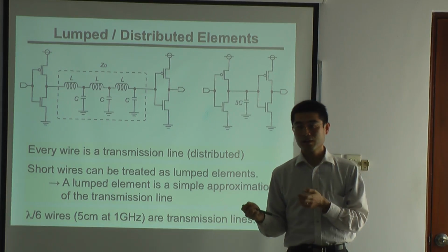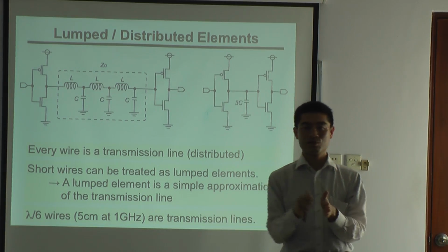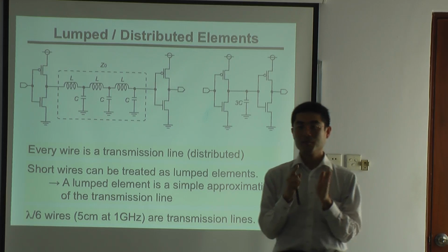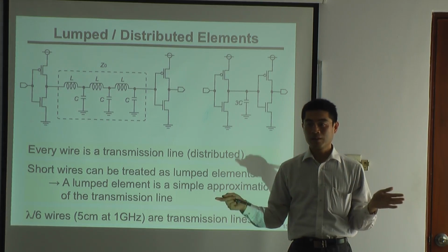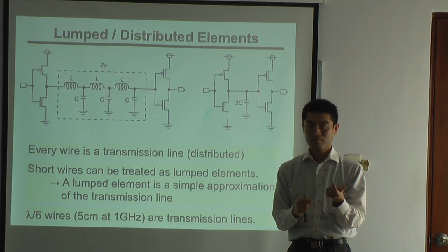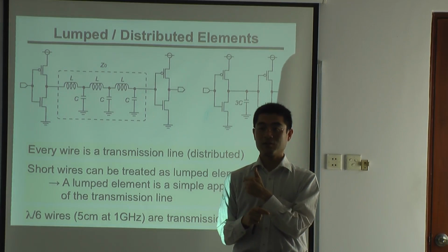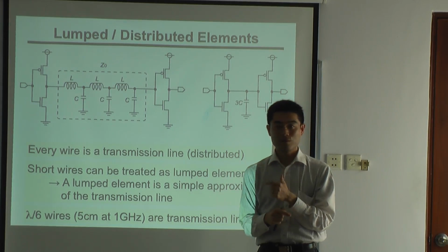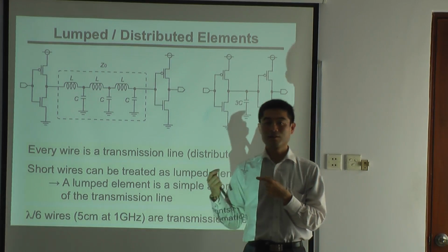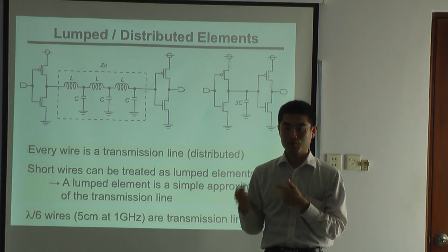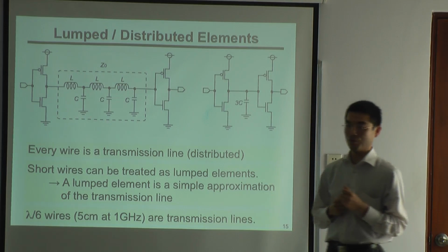If you want to communicate using 10 gigahertz, it becomes shorter, about millimeters. 100 gigahertz is very short. So in most cases, you have to treat it as a transmission line, calculate the reflections and simulate using L and C. And it takes time to simulate, so it will cause big problems.